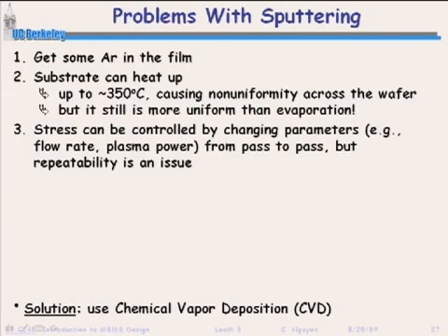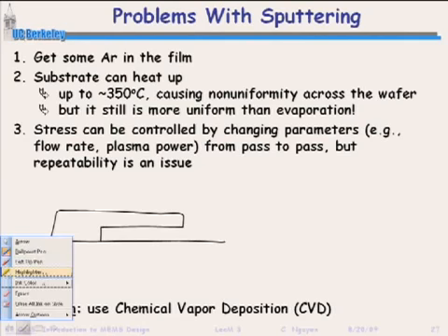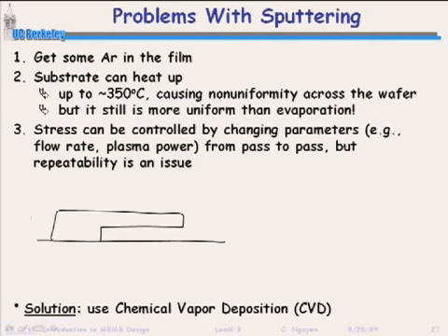So conformal means that you can cover things very well. Say I had something like this, a MEMS structure, and I wanted to deposit a film on top of this MEMS structure. Well, the film is going to be conformal if it can do this: come down here, go on this edge here, and be the same thickness everywhere. And then even get under this thing.